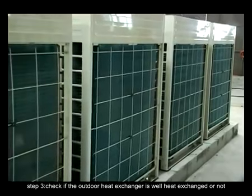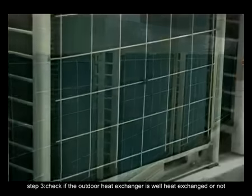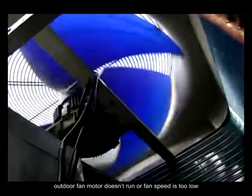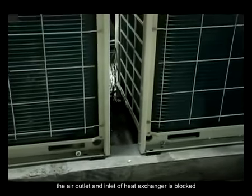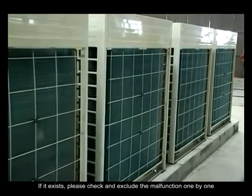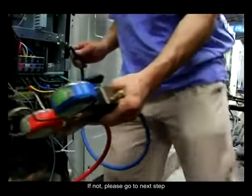Step 3. Check if the outdoor heat exchanger exchanges heat well or not. For example, the heat exchanger becomes dirty, the air outlet and inlet are short-circuited, the outdoor fan motor doesn't run, or fan speed is too low, the air outlet and inlet of the heat exchanger are blocked, the distance between outdoor units is too short, and so on. If it exists, please check and exclude the malfunction one by one. If not, please go to the next step.